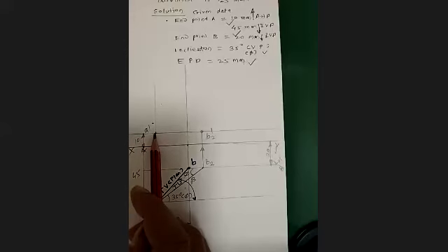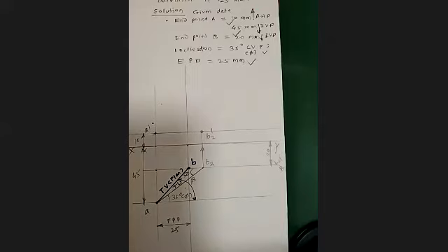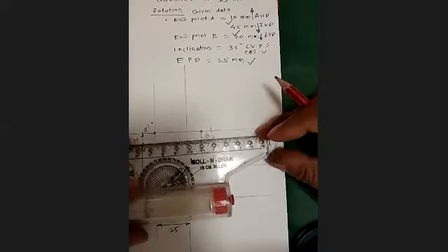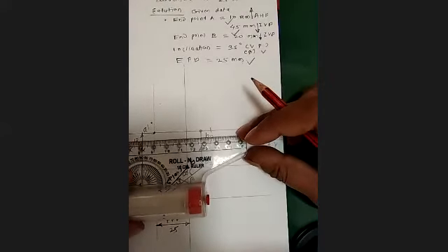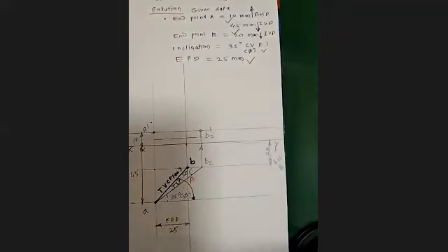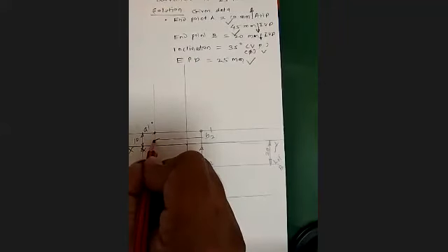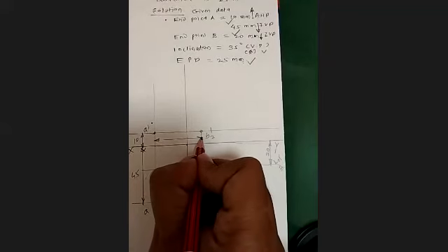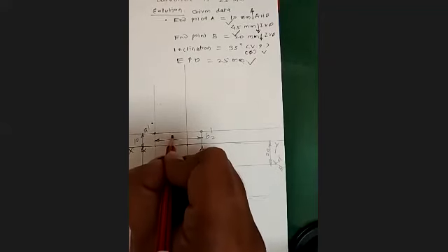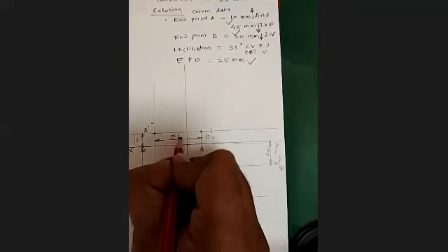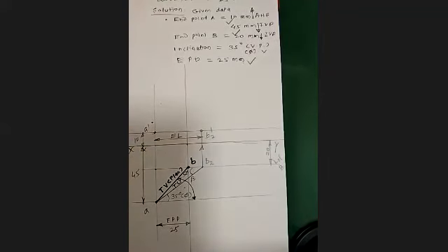What is the distance from A? What we can say, A1 to B2 dash? What is this distance? What distance are you going to get here? TL. This distance will be the TL distance, right? This distance is now TL. You can take a distance in compass equal to TL.